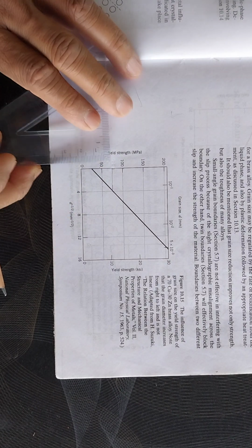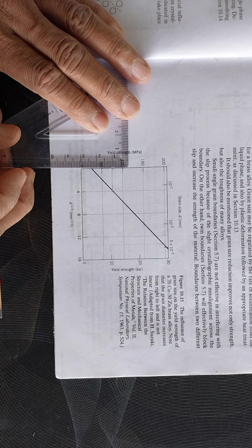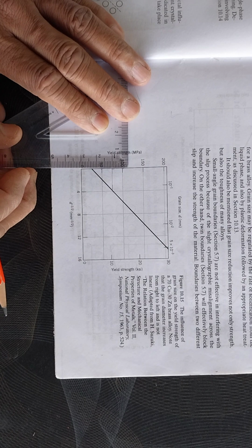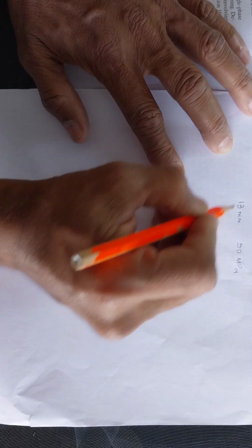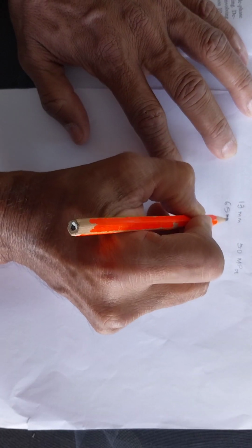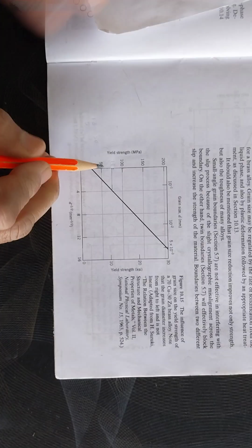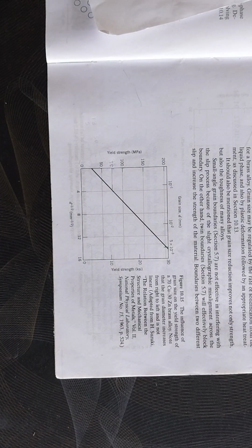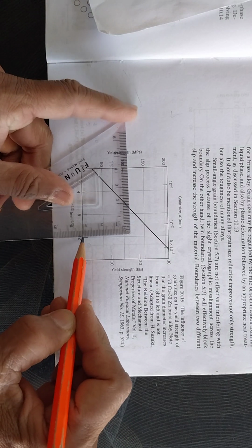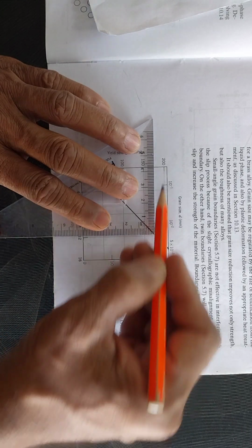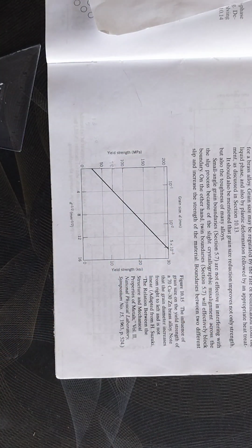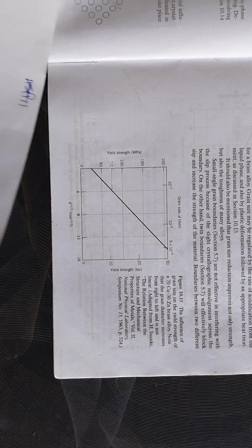This is going to be approximately 6.5 mm, so not much calculation required here. For 6.5 mm, you'll get obviously a difference of 25 megapascal. So the value here can be considered as 75 megapascals. In a similar manner, I'm going to take another point, 12, and when I drop a perpendicular, as you can see, that will work out to this point, which is 175.